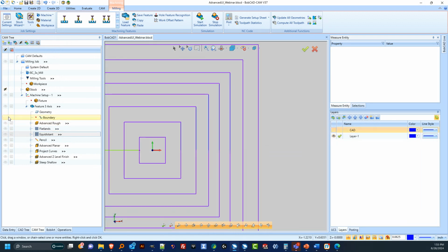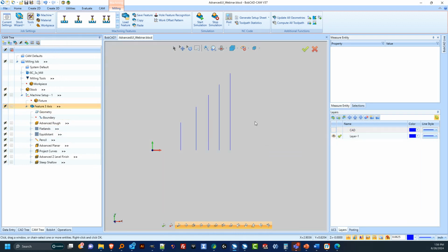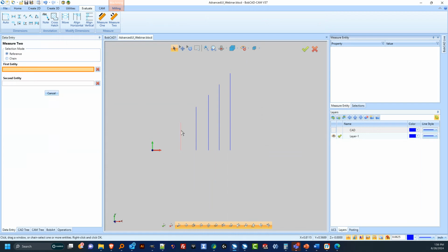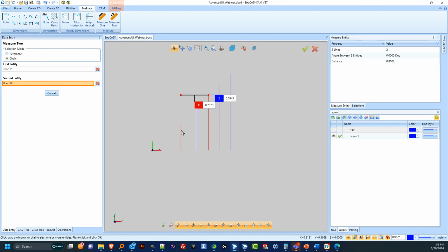Hide the original and hide the toolpath. Yeah, we can already kind of see it right here, it looks like. So if we evaluate this, this is on the floor of our part. We are 0.43 away. If we look at this chain, and this, yeah, 0.3 away. So yeah, it definitely does look like it's handling the walls differently than the floor to give us the proper cusp height in general.